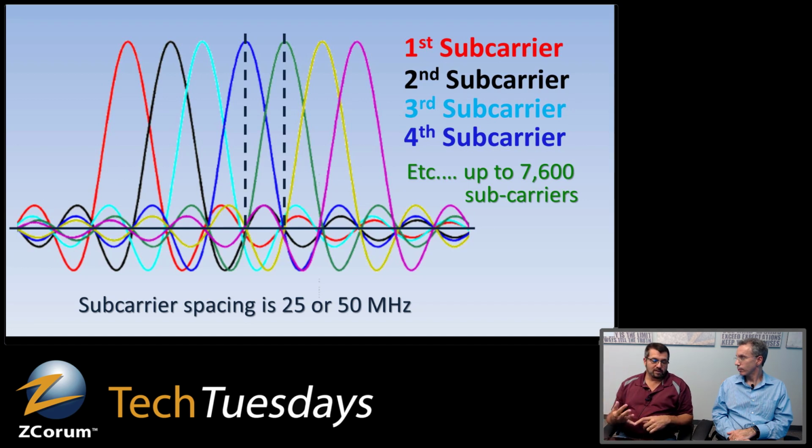So the way it works is you have a base profile, profile A, that every device that's going to do OFDM has to lock onto. And that's ironically for a lot of folks 256, which is like max in the 3.0 world. Right. But some will make 256 their base profile for the OFDM channel, and then have 512, 1024, 4096 for B, C, and D. Or I've even seen somebody do it differently, where B was really high. That was unusual. But usually, as you go up the chain, A, B, C, D, they're going to run out of letters at some point when they get enough capability to do profiles. They only can do 16 right now, but it's going to expand over time.